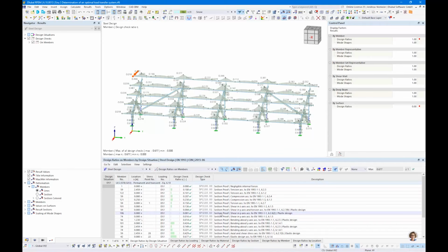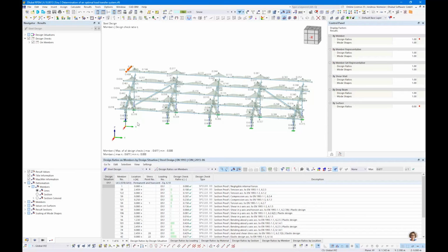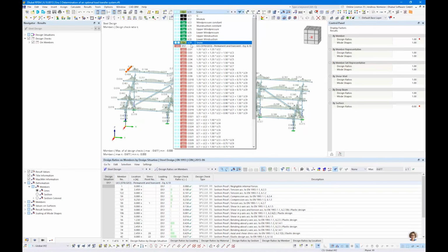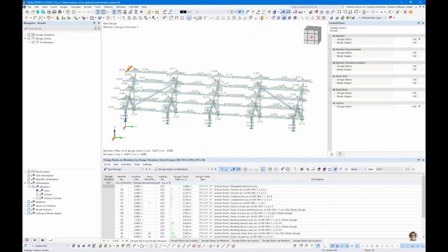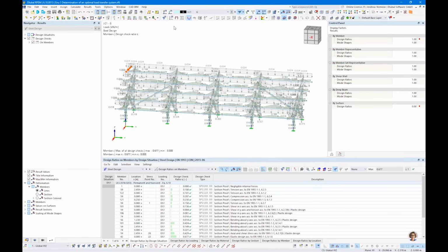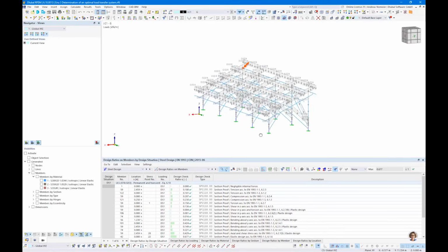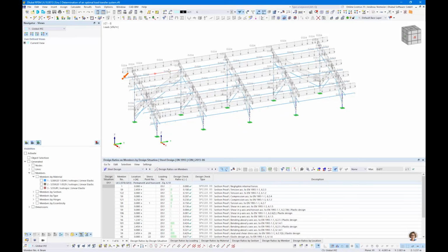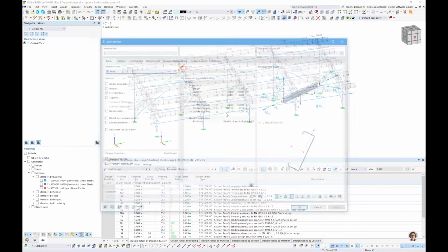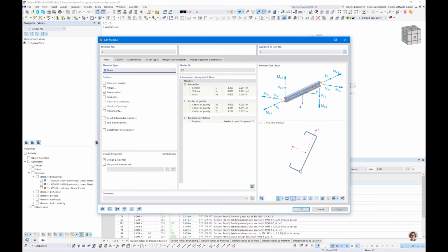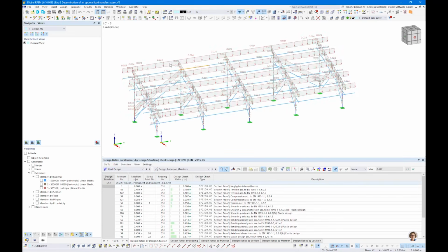But how do you come to this picture and what do you have to insert? For this, maybe start from scratch with what the engineer did here. The engineer defined primary load cases, so this upper part is coming from the engineer. He defined a self-weight load case. The self-weight is coming from the section. If you define a section, the program knows the size from the section and the material and can detect self-weight automatically. If you change it, it will be changed.